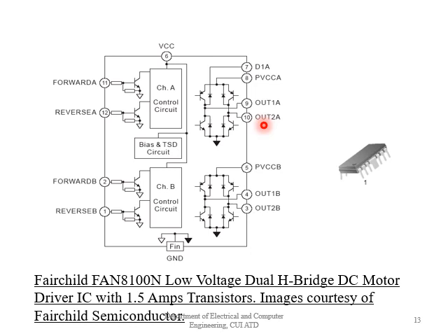By pulsing the drive circuit on and off, so we can turn this circuit on and off at several kilohertz, the speed of the motor can be controlled. So how can we control the speed of the motor? The speed is proportional to pulse width. As I've just told you in the previous slide, once we increase the duty cycle, the voltage will increase and the speed will increase.